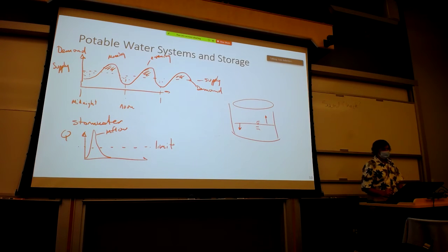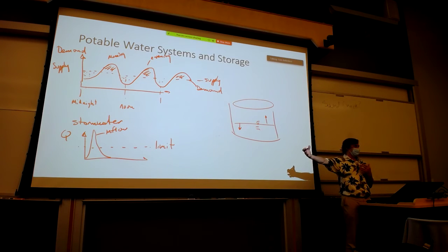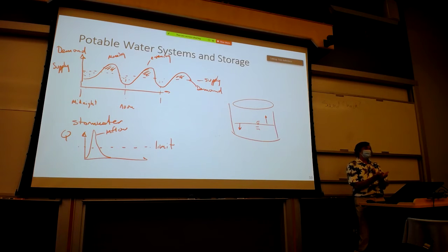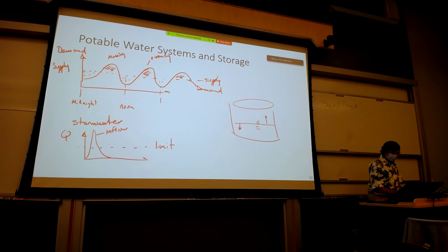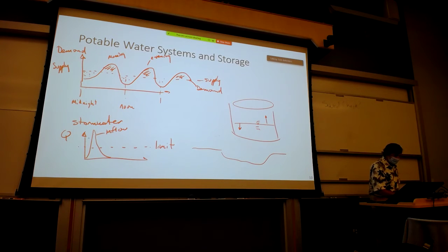And we may have required maximum or limits on how much runoff we can have from the site. That's really common. We typically limit the runoff to not to exceed the pre-development runoff peaks. And so what we'll do is we'll build a detention pond, or we'll put in some other device where we can temporarily store water.